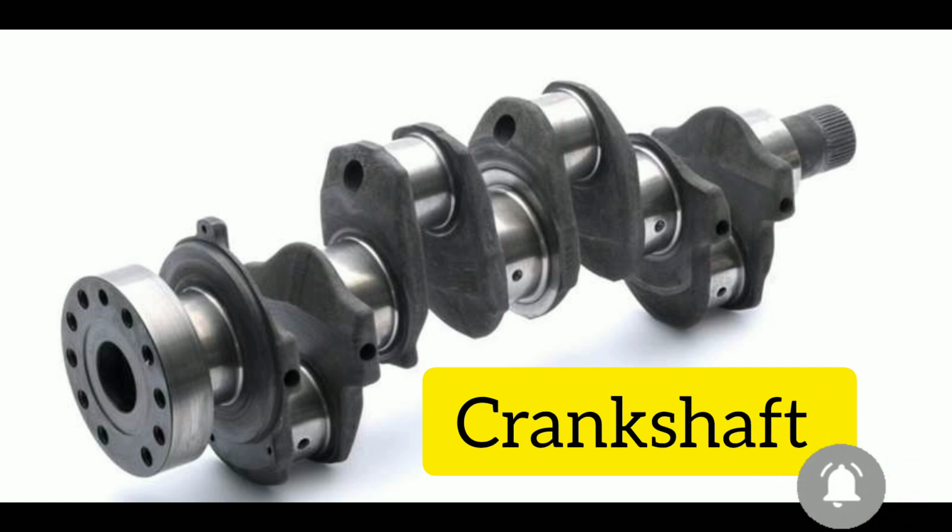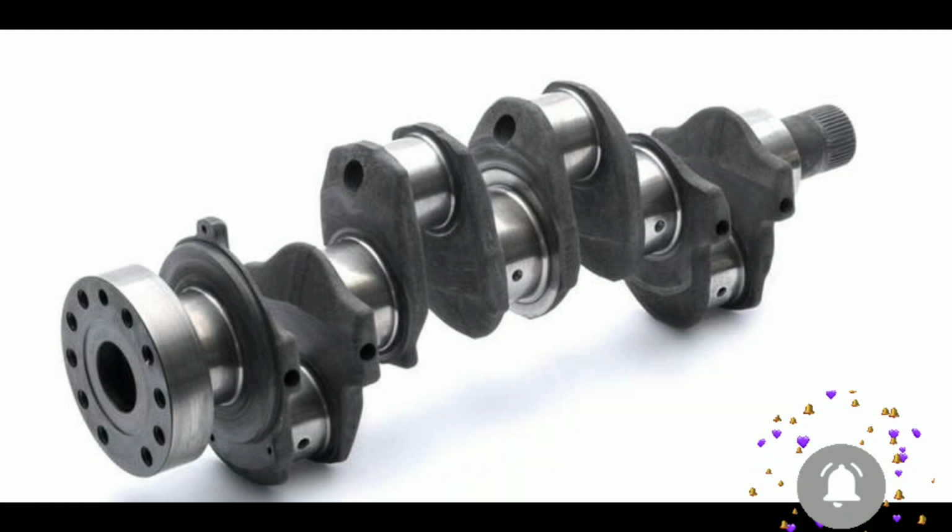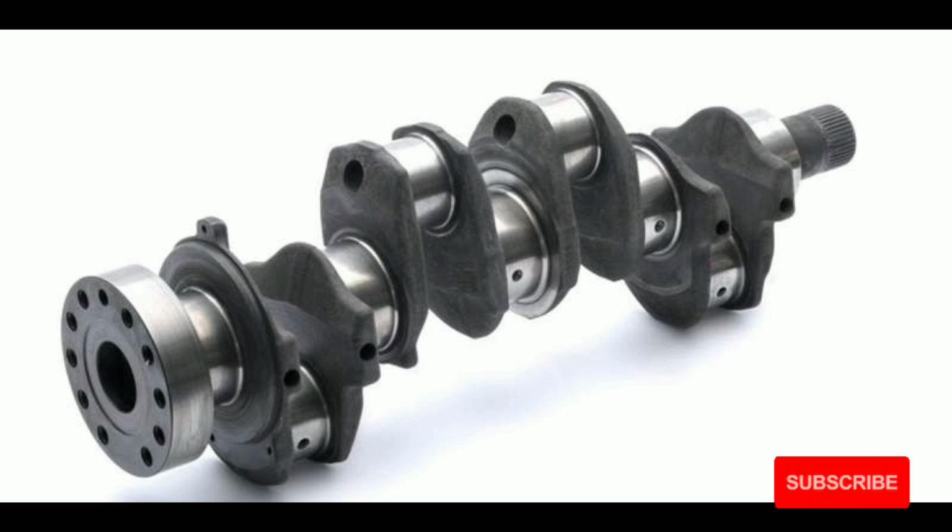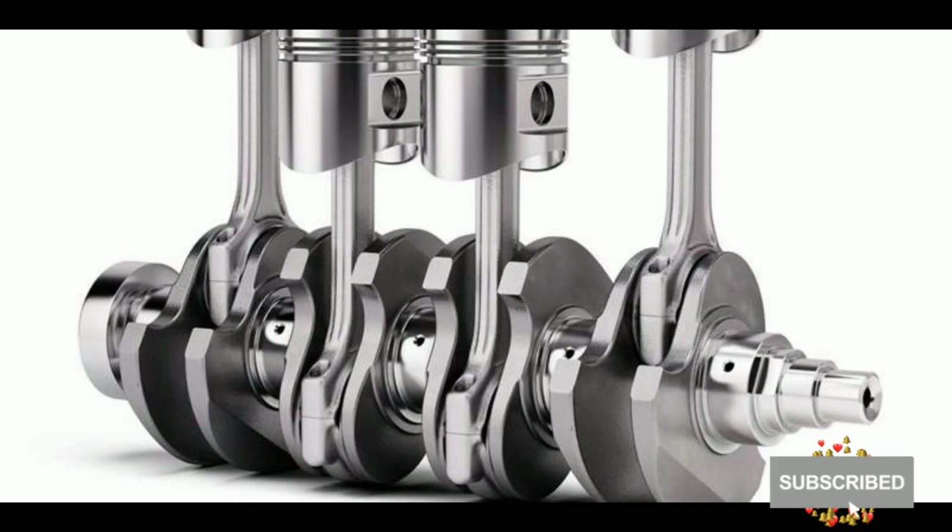It has another purpose. It generates rotary force from the torque of the connecting rod, and it drives all accessories of an engine via its pulley. The crankshaft drives all engine accessories through different pulleys that are connected to the crankshaft pulley, and it is where the flywheel is connected. This is the piston, connecting rod and crankshaft together as one unit.